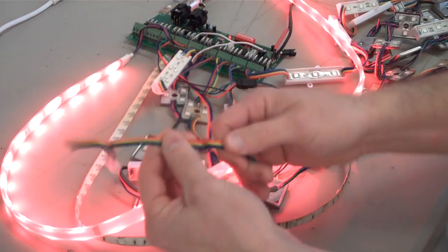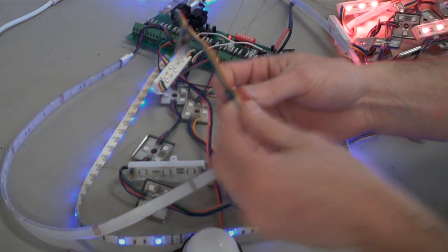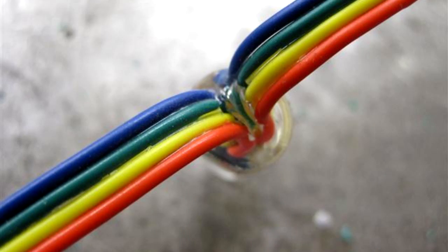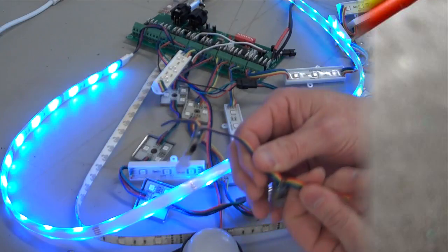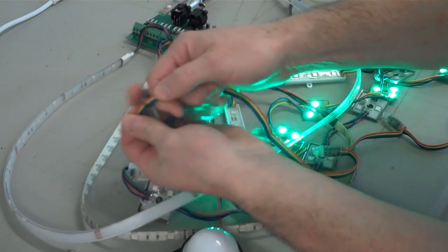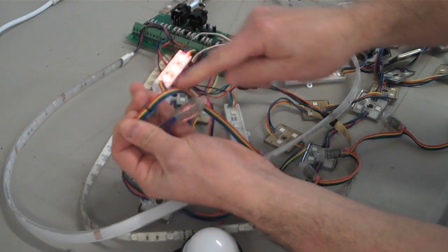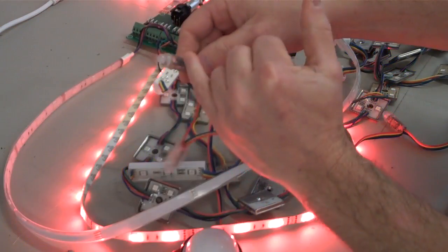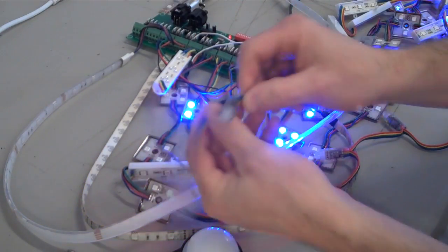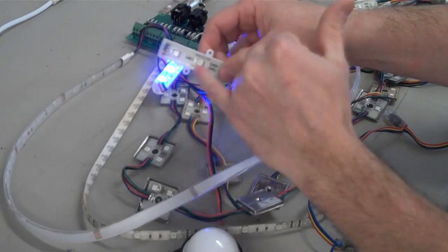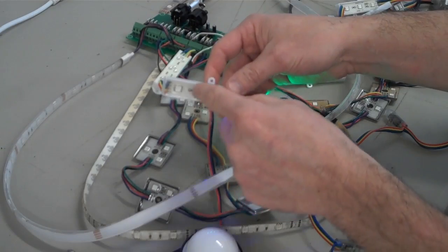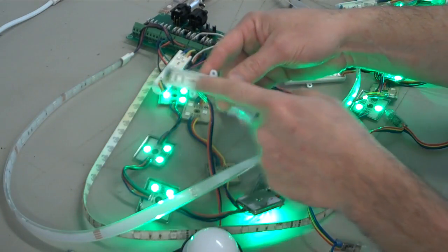Now, one of the common problems with these particular types of devices is that there is often a gap between these particular nodes, and that can allow water ingress into the nodes. In these particular ones, you can see that there's quite a bit of gap in here, and as the water comes down the line, it can get in there and short-circuit the board. So quality concerns are always an issue for these kinds of devices. Not so much on these types or on the strips, because these are usually 100% sealed with some sort of clear epoxy or plastic.